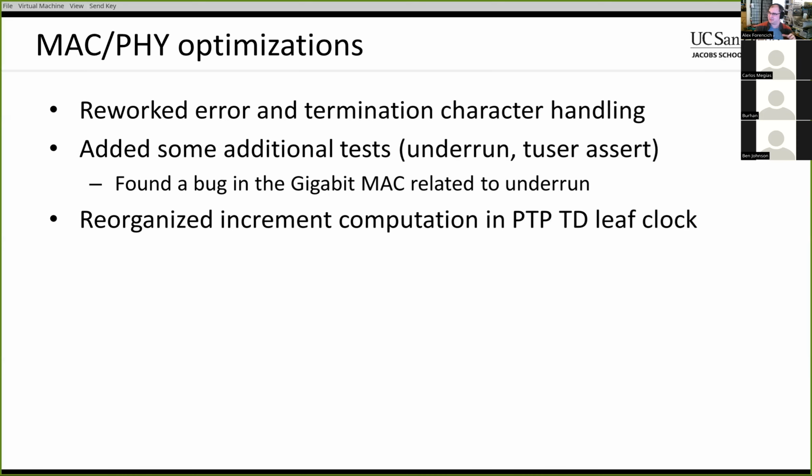And if you know about how the FPGAs are internally built, inside of each slice, you have a LUT and you have a flip-flop right there next to each other. So if you don't use the flip-flop, it can actually be difficult for the tools to use that flip-flop for something else. So by trying to save flip-flops, you might end up using more LUTs, and then those LUTs can potentially prevent the tool from using some of the associated flip-flops later on. So the end result might be even worse than just using a few additional flip-flops.